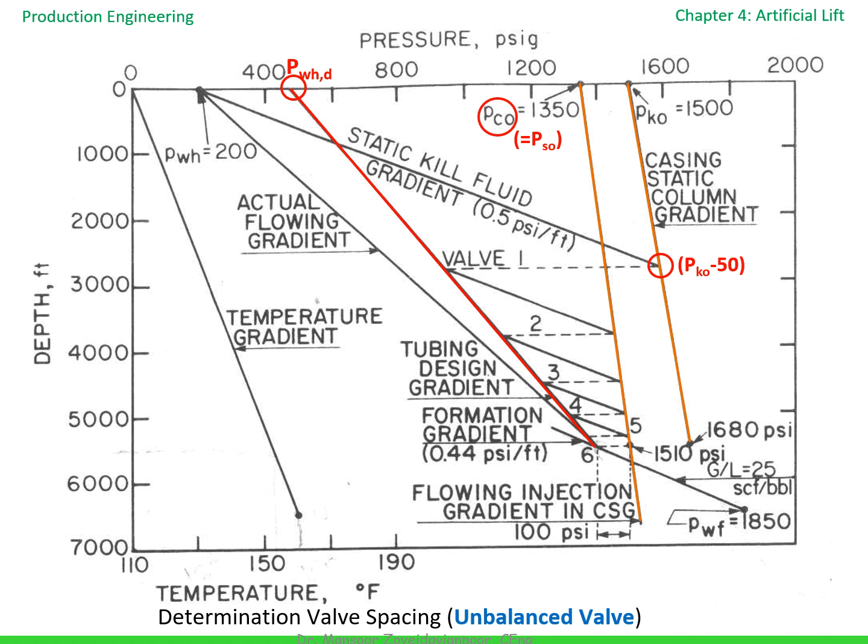The objective remains unchanged. Each valve should open, unload a portion of the fluid column, close, and then hand over operation to the next deeper valve until the operating valve is reached. So the physics is the same. Only the pressure reference used for valve placement changes.